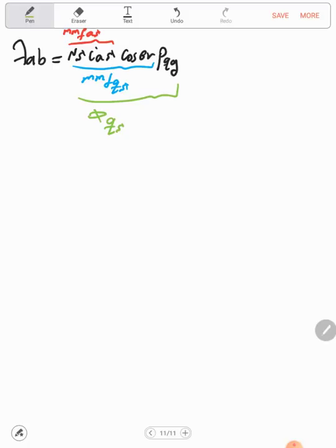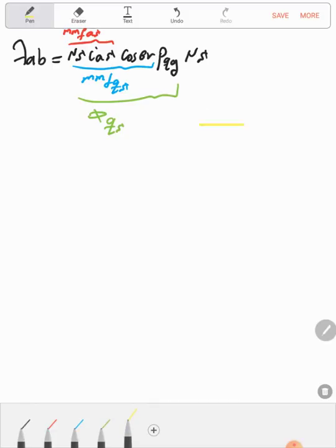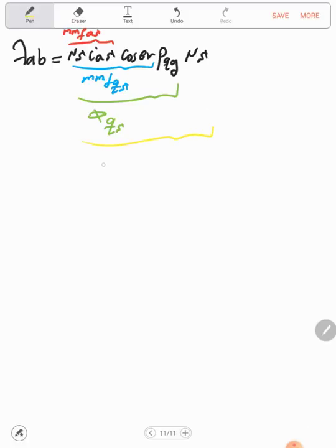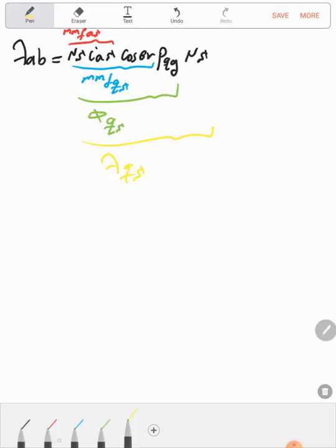Now if we multiply it by NS, this would be the flux linkage lambda QS. Now if we project it, let's say, to the phase B, we need to multiply it by cosine of the angle between the Q axis and the B axis.